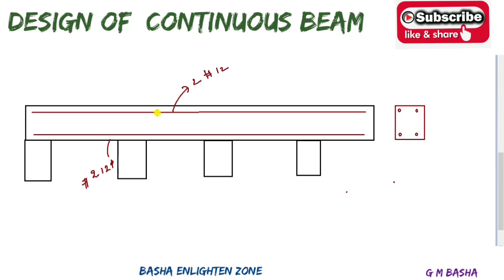I will provide that also here with the green bars. So I will choose to keep one more bar here. So 2 bars. I will stretch them side by side here. 2 bars I will keep in the same line. Automatically it cannot be visible. It will be visible on the upper side like this. So totally there will be 4 bars. Okay. At the supports 2 bars, and at the overhang, including overhangs, total number of bars will be 4 bars. So exactly if you look here, 4 bars are at the supports including the overall beam.